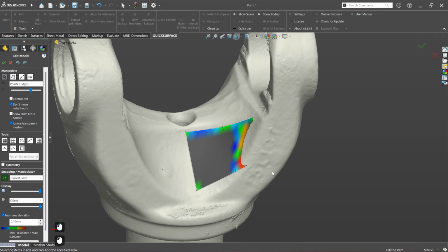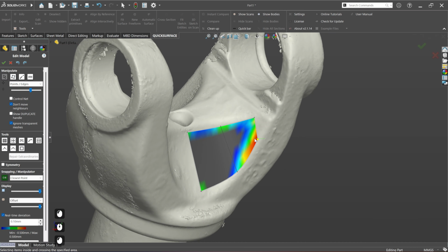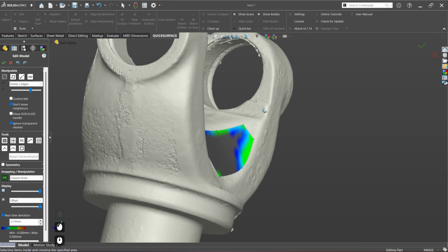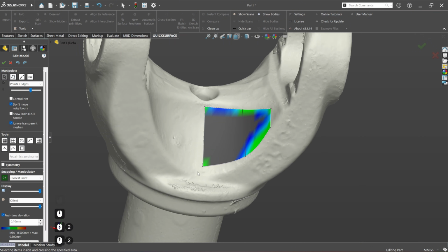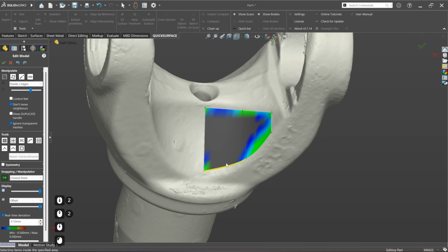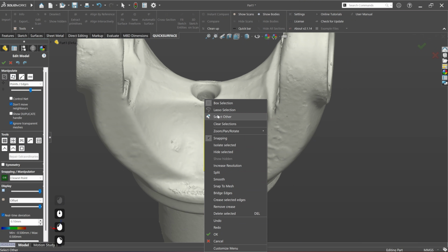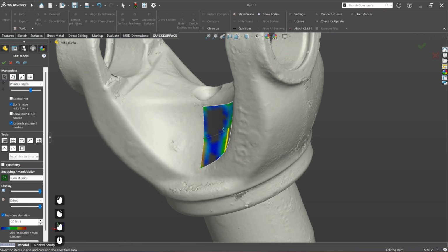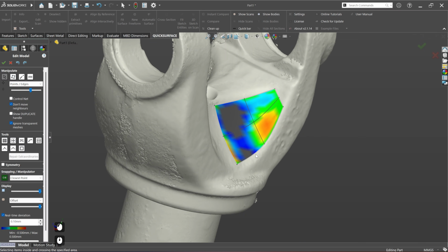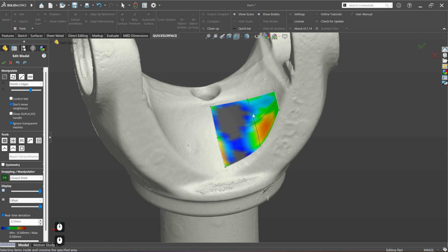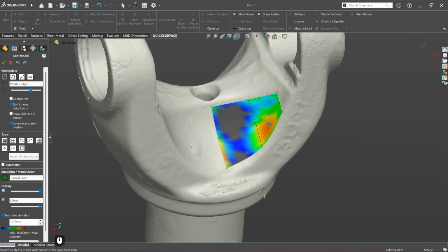Maybe in this case I'm going to still use snapping on and reposition the points of our freeform to match our shape better. Only reposition this one, maybe this one a bit. And now I want to split these edges in half.